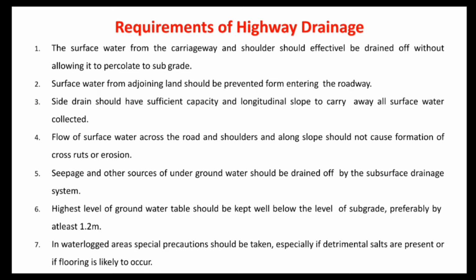Next, the side drains should have sufficient capacity and longitudinal slope so that the water may be discharged with ease. And the flow of the surface water should not cause formation of cross ruts or erosion. Next, the seepage and other sources of underground water should be drained off.